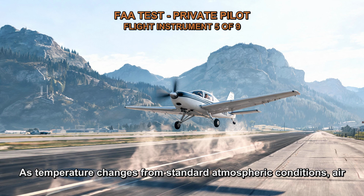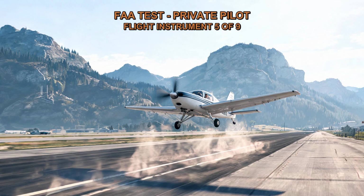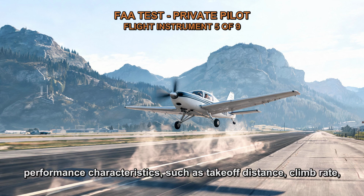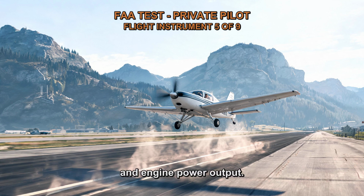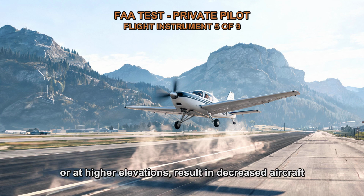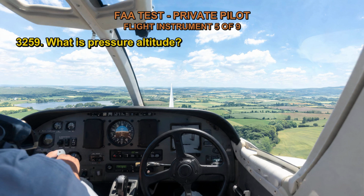As temperature changes from standard atmospheric conditions, air density also changes, which affects aircraft performance. Density altitude is used to determine an aircraft's performance characteristics, such as takeoff distance, climb rate, and engine power output. Higher density altitudes, which occur in warmer temperatures or at higher elevations, result in decreased aircraft performance, as the reduced air density affects lift, thrust, and other factors.